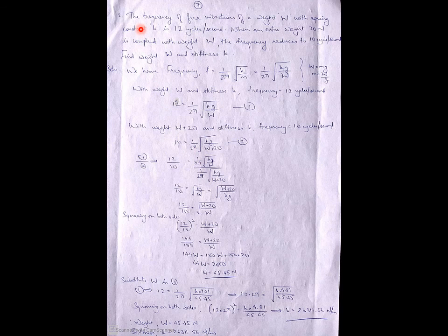Now all these are in SI units. This is 50 Newton, 4 oscillations per second or hertz. So finally you will be getting it in SI unit itself, which is Newton per meter. Now what we want is in Newton per centimeter. So convert this meter into centimeter, so divide this by 100. Finally you will be getting 32.16 Newton per centimeter. Let us see the next problem.